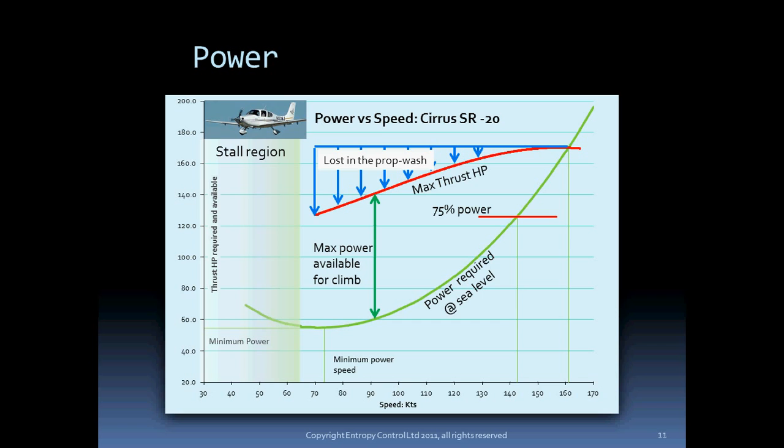If, say, you're flying at 85 knots, initially you'll get a little altitude fillip as you slow down and the excess speed is converted to height. After that, because you're flying now at say 75 knots, where the power requirement of the aircraft is lower and the engine output is still about the same, you will get a slow climb, which is what you want.